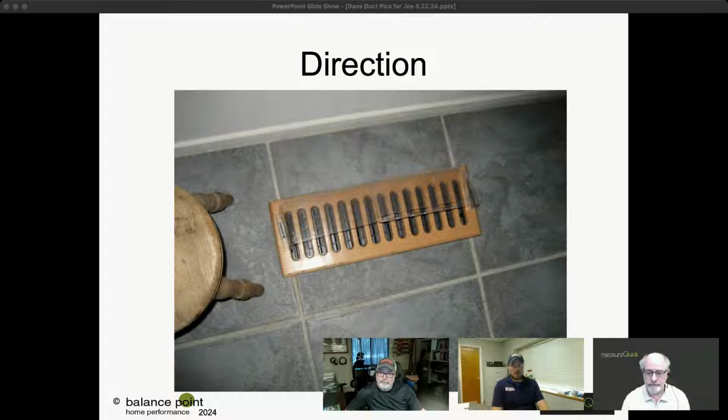A couple months ago, I had a customer with a very contemporary house, and there's only an attic over part of the house where we were putting the equipment in, and his living room was 20-something feet away. So how do I get air from over here all the way to his other wall? It's really just register selection, getting the right register that's able to throw the air almost as far as I needed it to. And he's been comfortable since.